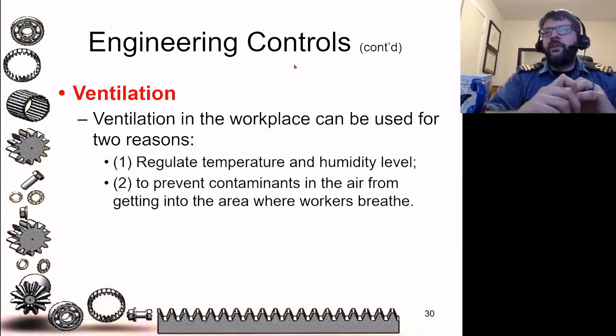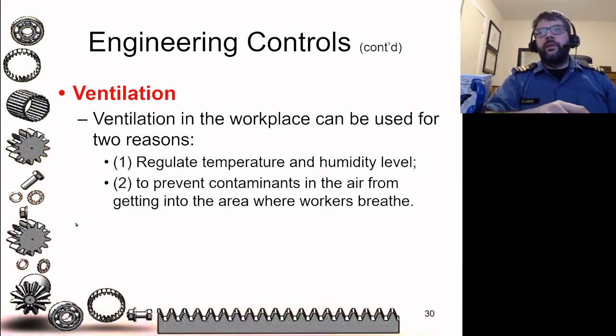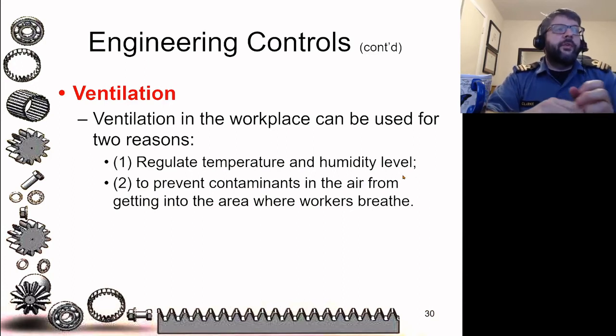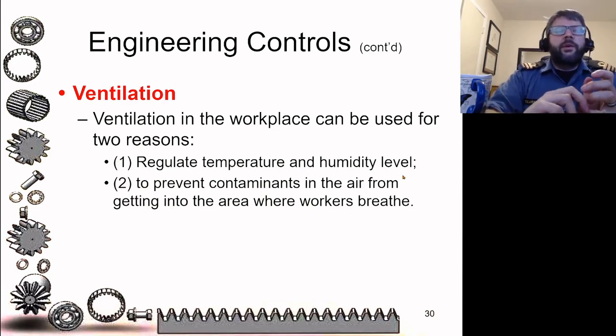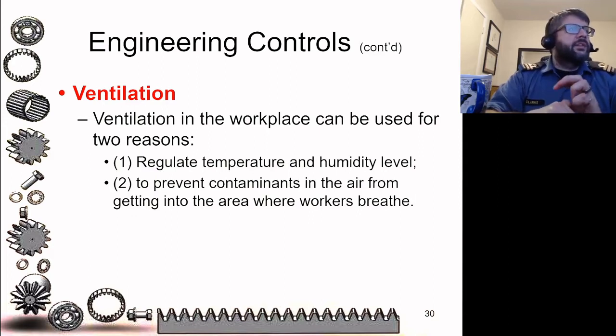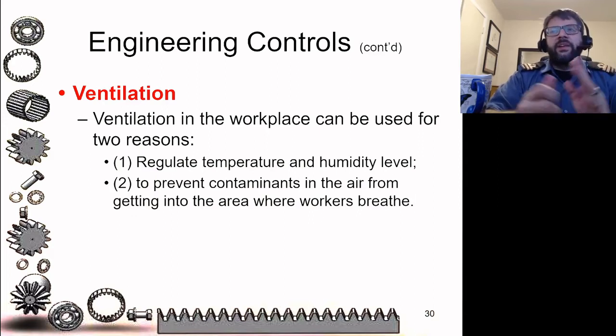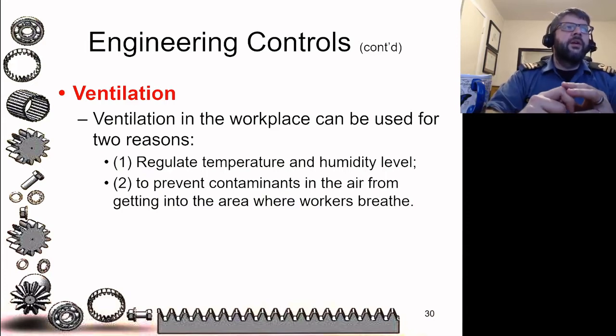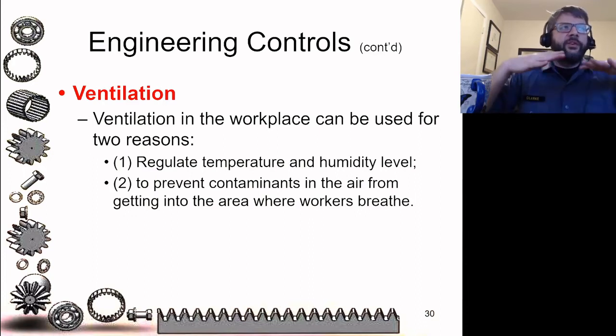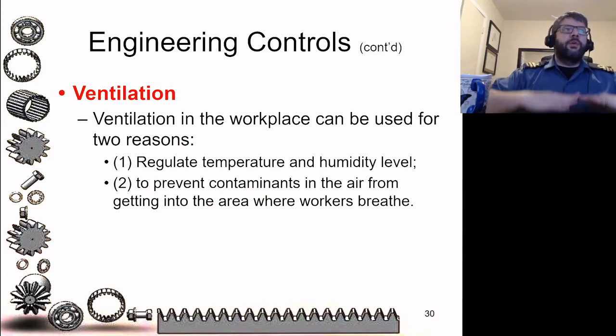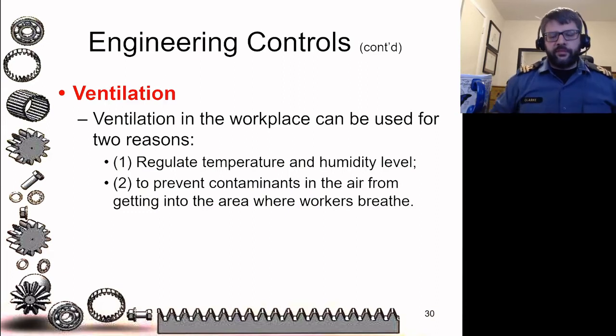Ventilation can be very helpful. Regulating temperature and humidity levels is fairly important, and we don't want people to be uncomfortable. We don't want them freezing. We don't want them getting heat stress, and so on and so forth. And then, of course, keeping the contaminants in the air from getting to where the workers breathe, or if you can't eliminate that completely, keeping levels of the contaminants below a certain safe threshold.